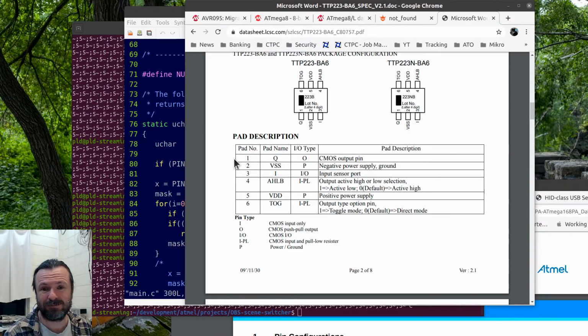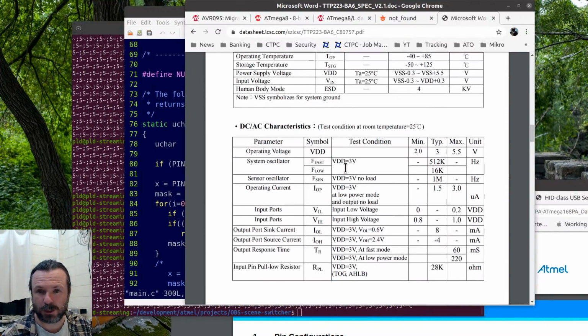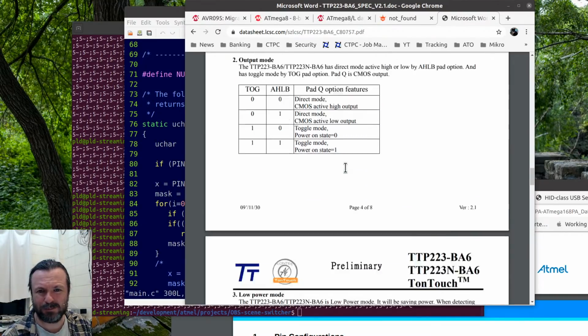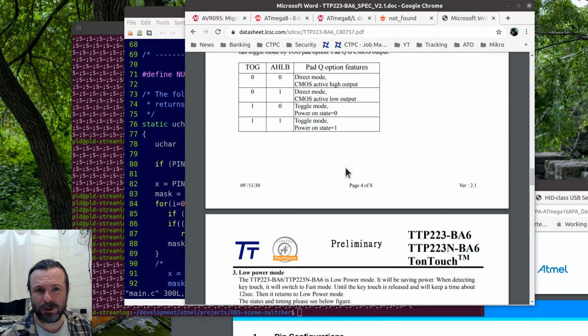So it is as would be expected. Now what I could do is replace this 1K2 with a 0 ohm, if people are concerned that the 1K2 has given it too much of a float. But I'd be pretty shocked if it was in float.